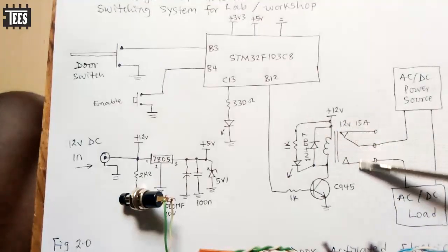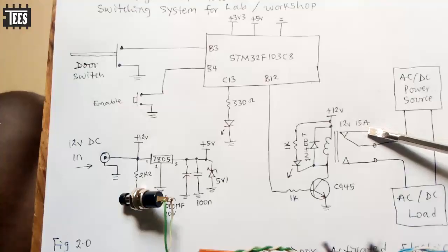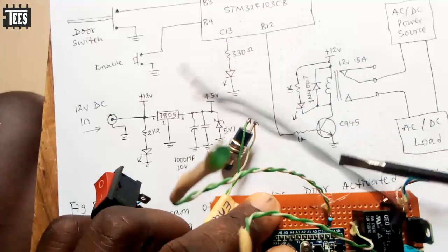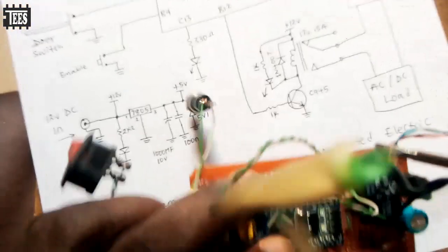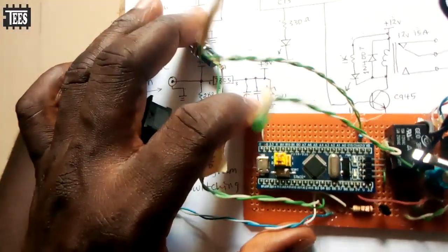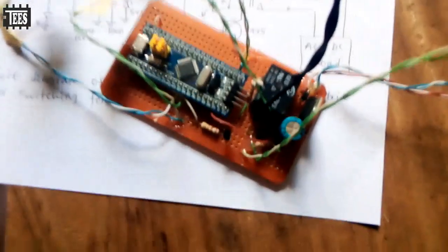You understand? So the relay, you can use it if your load is less than 15 amps. If your load is less than 15 amps, and you are putting this in permanently, make sure you use larger cables. You understand? Based on your requirement. So for real life, if you want to put it in permanently, make sure the size of your relay should be twice as high as the total load that you are using. You understand? So that is all we have for today.